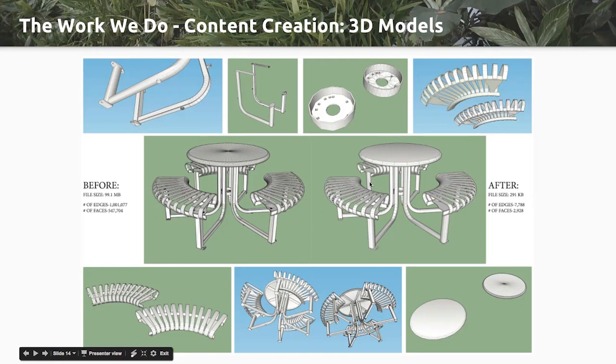Setting something up that is more functional is only going to help your SketchUp files, and for those who do use SketchUp, this is a big concern once you start building that 3D model, that 3D site, and it just slows down your computer. It's all because of the lines, the faces and the edges. The fact that we have over 1 million edges in this one and only 7,000 in this one is a huge, huge difference, let alone just the faces.